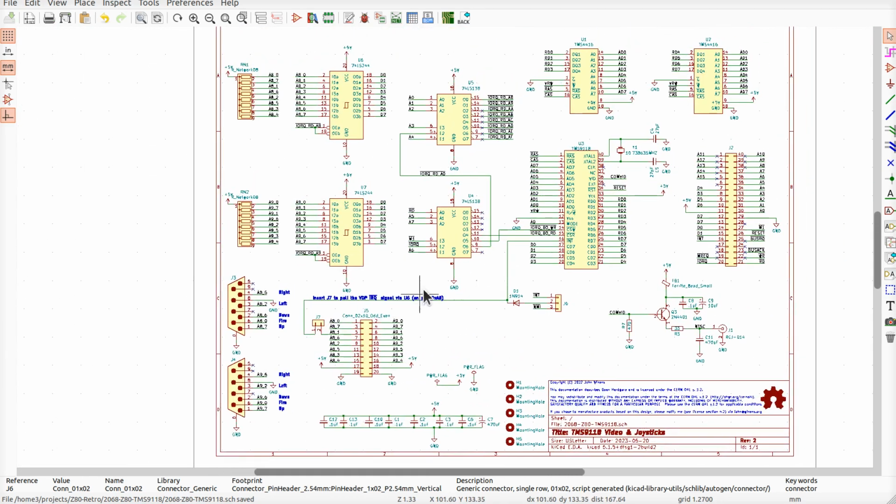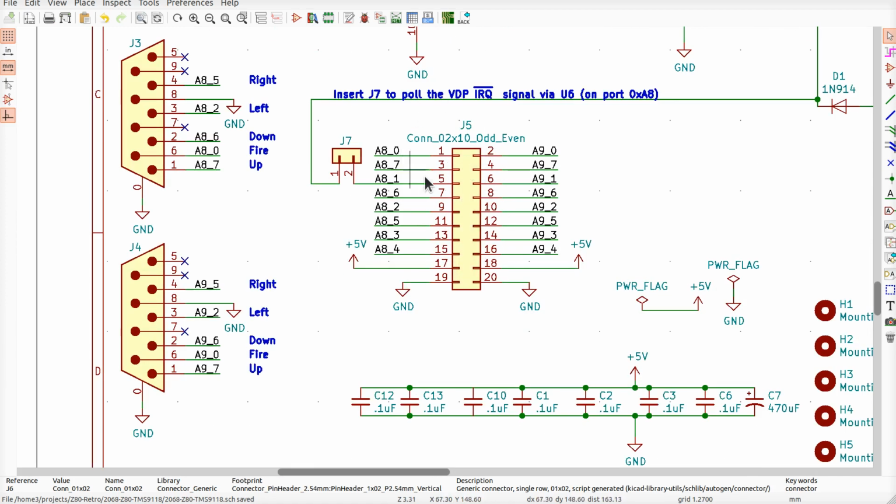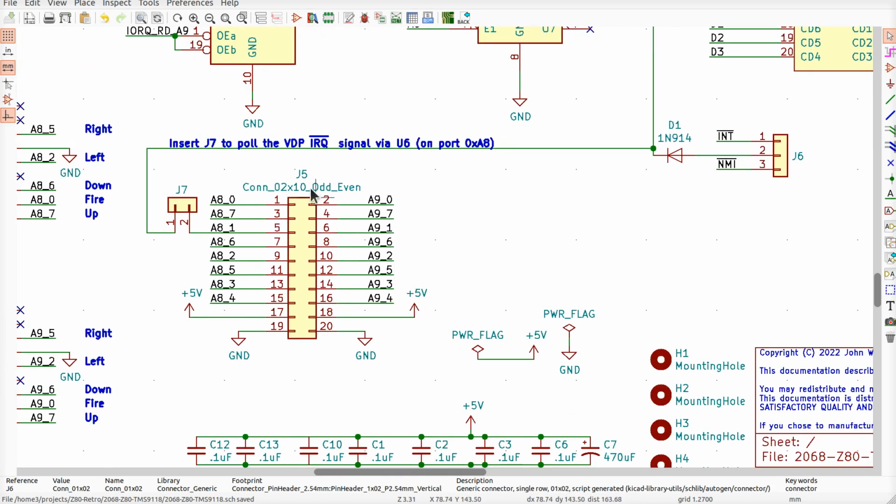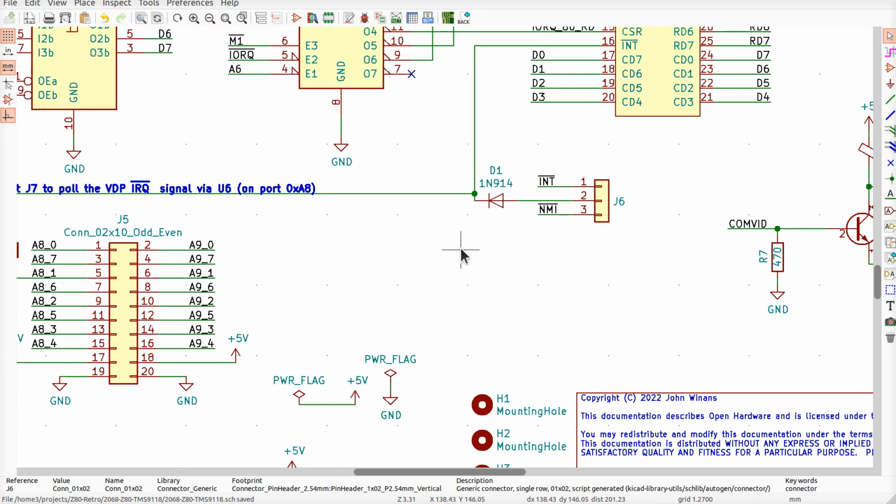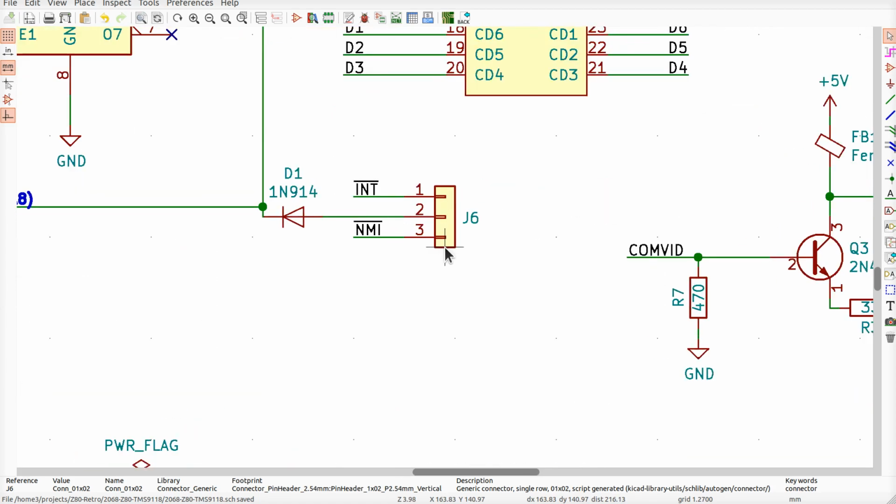Any of these single row headers you can use for all these little shunt blocks on your retro main board and stuff like that, okay? You can also put 2 of them in a row right next to each other on a header like this. But if you do that and you're new to this whole thing, be careful how you solder them in so they don't end up pigeon-toed or akimbo. Then you end up not being able to put your header and stuff on these things. So be careful about that if you go that route.